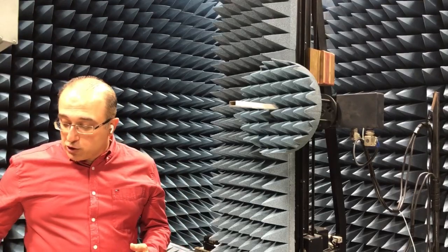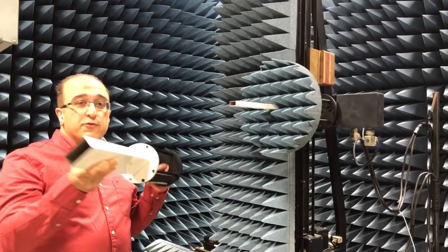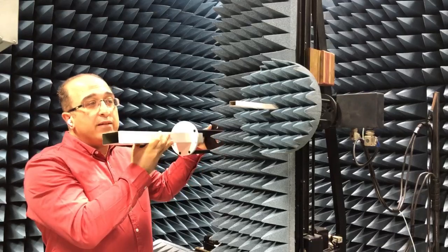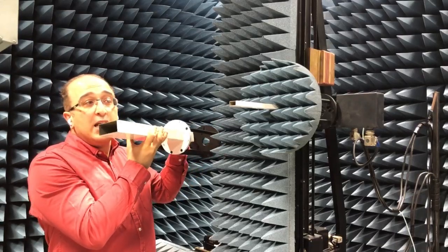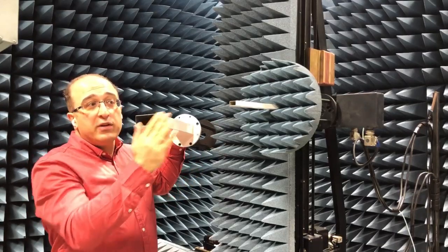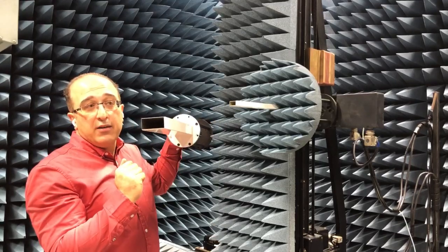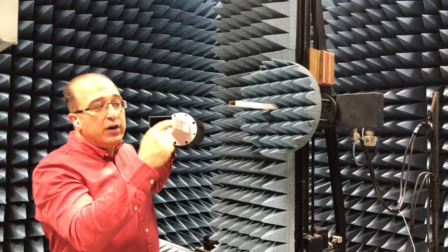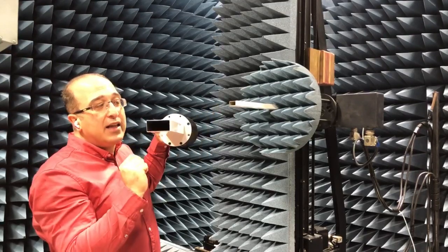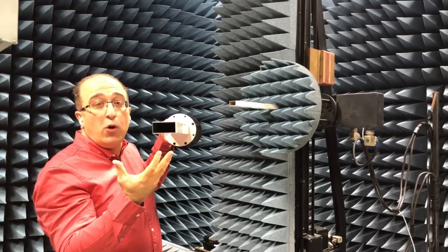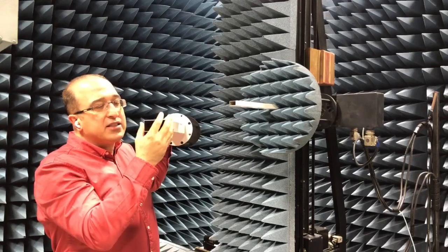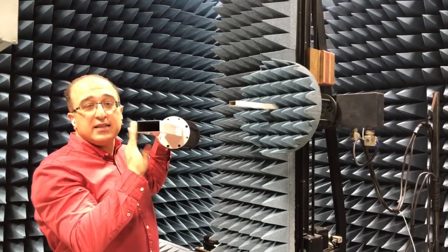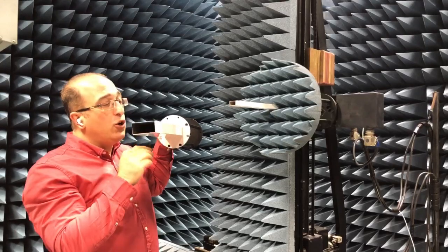So now I'm going to show you a waveguide which is for lower frequency, and if you compare it with that, for the same field distribution over the aperture of the two waveguides, so exactly the same thing, maximum here and going to zero here, which is our fundamental mode. The physical size of this is of course larger, because this is operating at lower frequency.